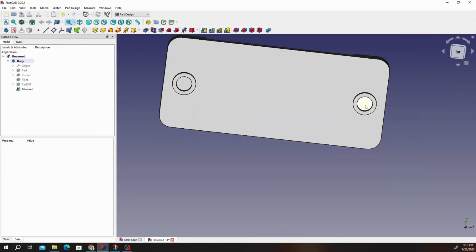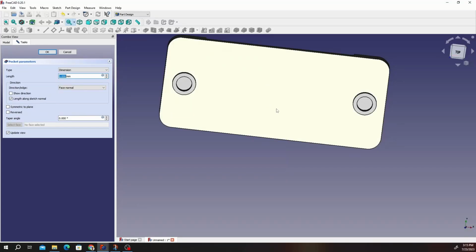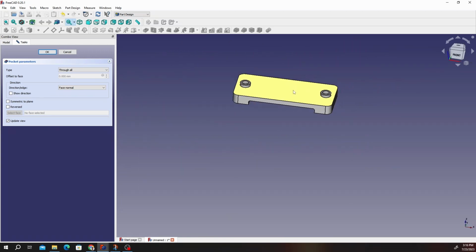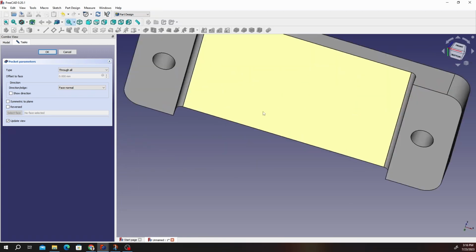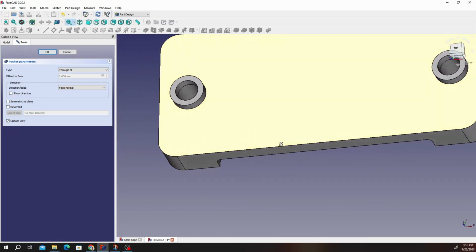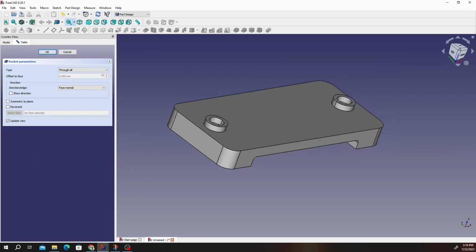Rotate it around, click that face, click on Control, click on that face, and then pocket, right? And then change this to through hole. And we should have something of the sort. Okay. So we should have the holes going through all the way in these 2 holes. So there we go. We have our platform.